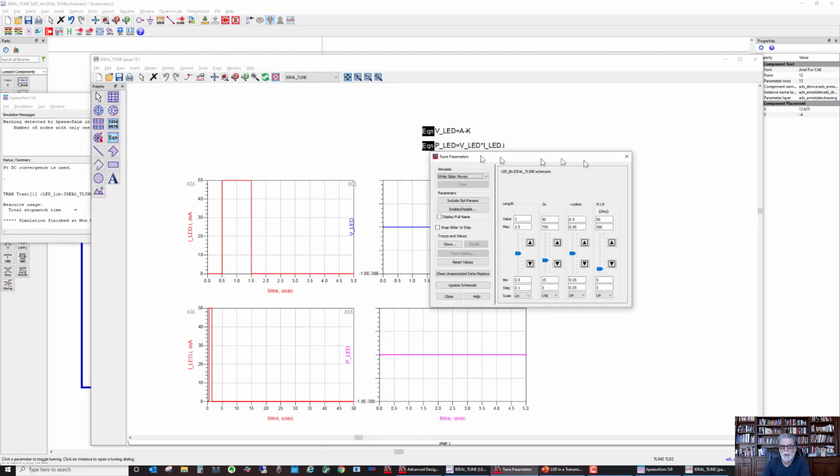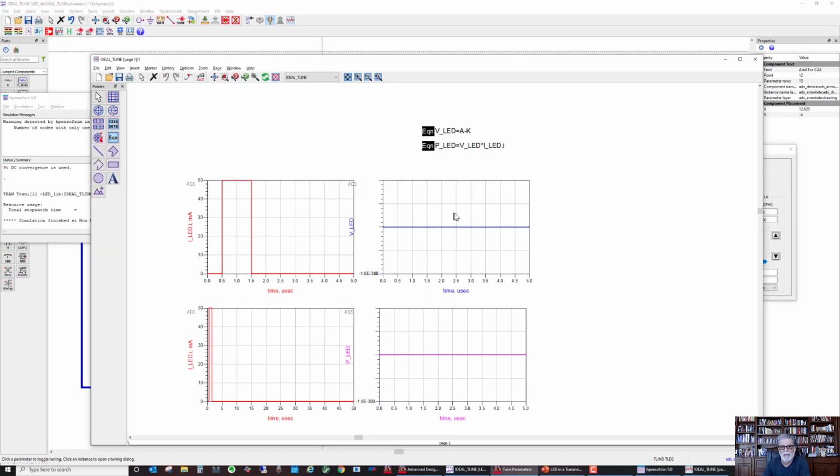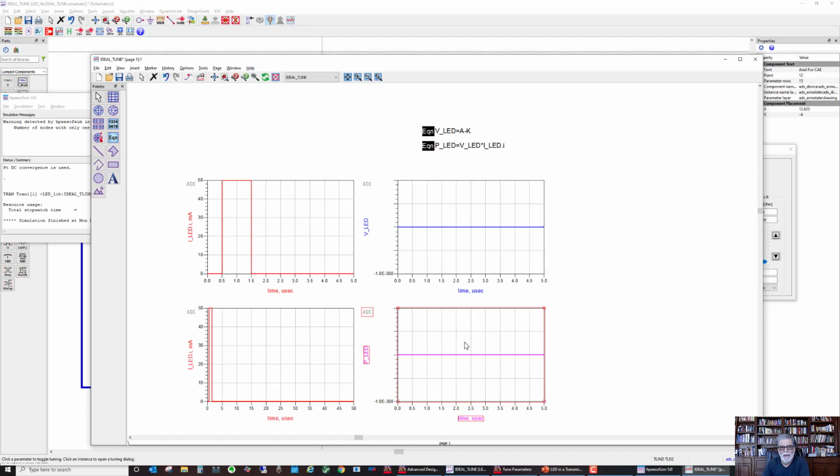So now I'm running into an open cable. I have the small signal and large signal impedances here on the right, and I'm looking at the pulse current, and you'll notice in this pulse on the left hand side I got 2 plots that are the same except for the scales. One is 10 times the scale of the other. So in the near term you can see that I have a 0.5 microsecond delay before I get to the first cable. That makes sense. It was halfway to a 1 microsecond long cable.